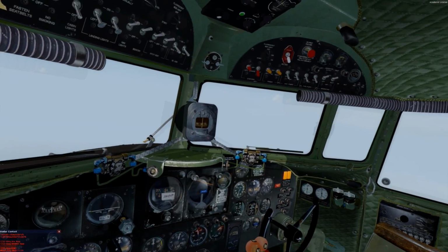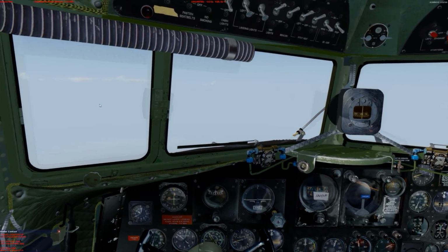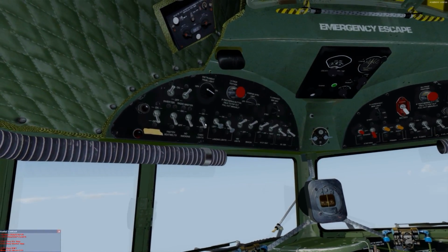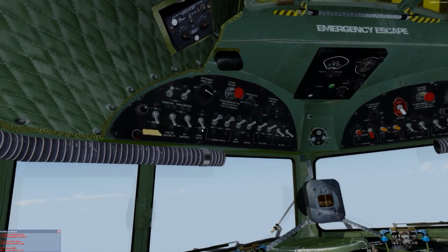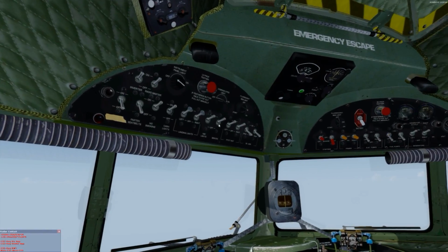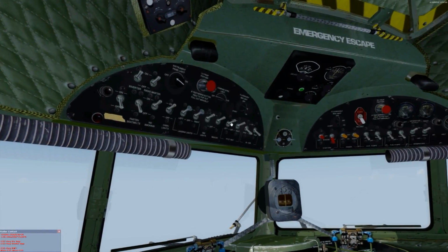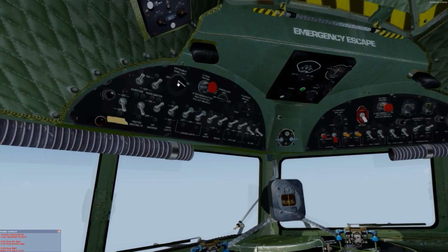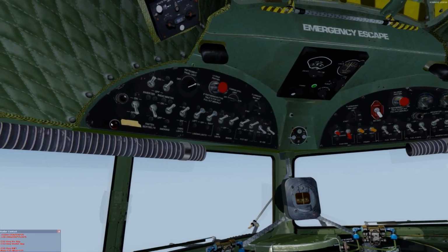Descent flow. Roger, descent. Seatbelt signs switched on. Yes, Captain. What can I do for you? No smoking, seatbelt and landing lights just to let you know we're commencing descent per your instruction. Okay, thanks. Lights switched on. Taxi lights selected on. Fuel pump 1, 2 switched on. Check altimeters are at QNH, David.